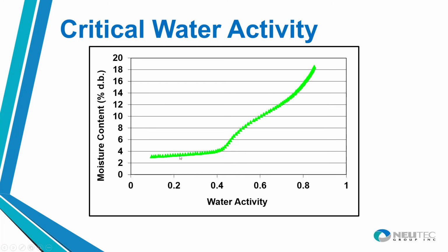When it's processed through spray drying and other approaches, the spray drying process puts it in this amorphous glassy state as opposed to a crystalline state, which is a more stable condition. The advantage is that these amorphous powders are more easily instantized. That's one reason you would process it that way. But also, as long as you can keep it in that glassy state, it will be metastable. It will have a very extensive shelf life. We're talking years.